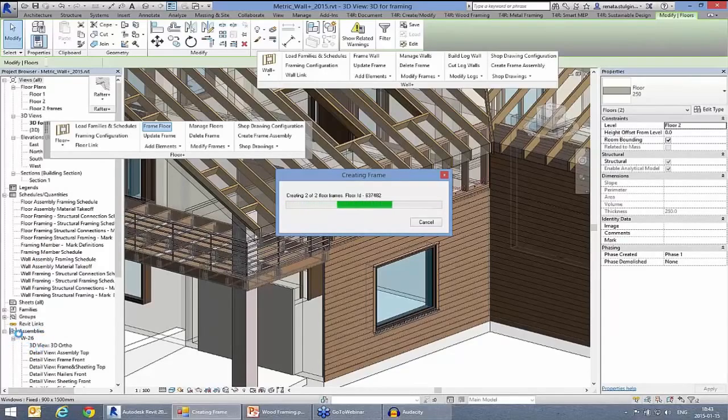As you can see, for example, this assembly that we did for this wall has the name W26. So this is the number from the wall. This is a mark value from the wall. So you have to be sure that your walls or floor panels are marked, because later that will be used in making shop drawings.